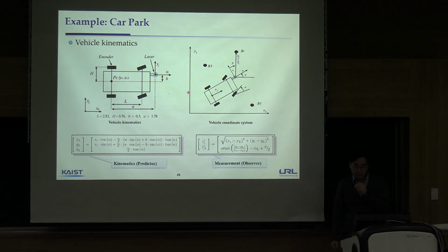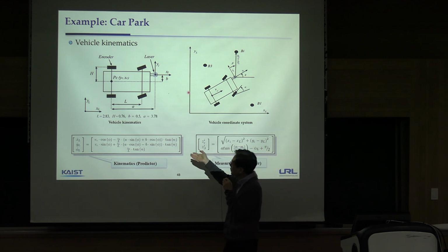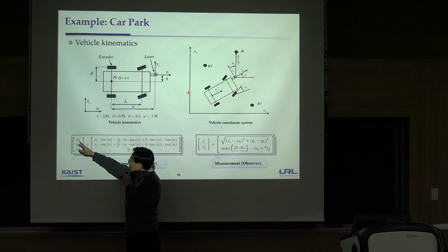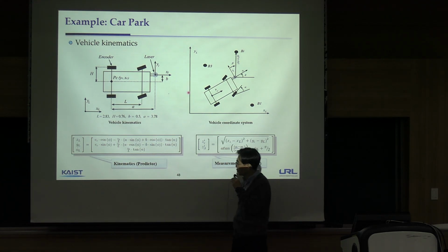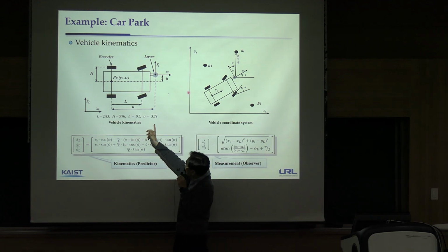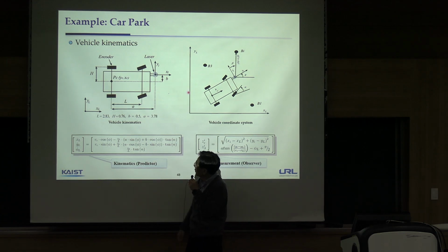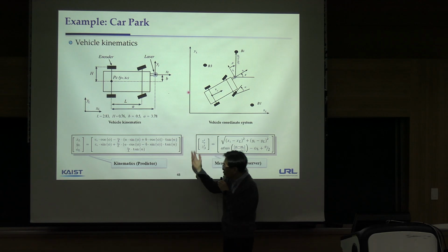And we have the vehicle kinematics like here. This is the car-like vehicle. So the vehicle will be governed by this dynamic equation: x dot, y dot, and theta dot. Orientation will be governed by this equation. So this is given. All the dimensions we know, L, a, b, they are known in advance. So using that, we can predict the next position of the vehicle.